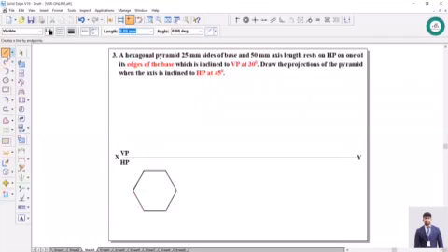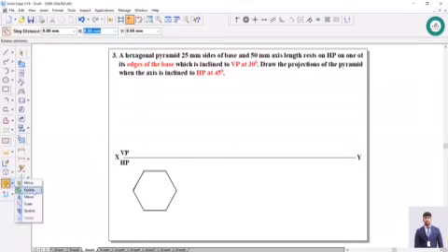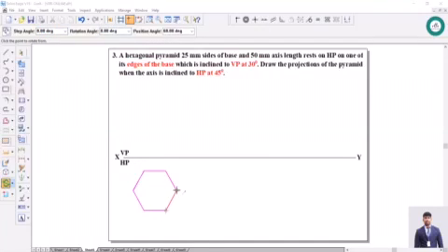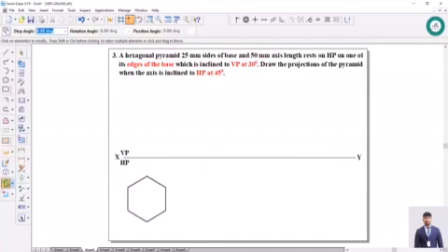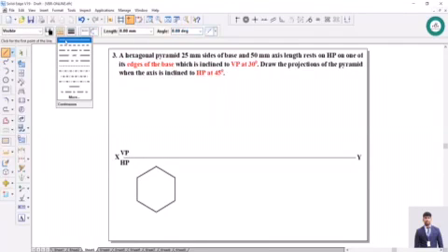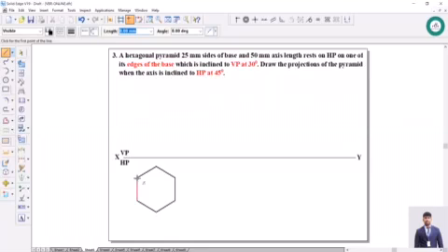Next, since it is an edge condition, go to rotate, select this particular figure, select one edge and make it vertical. So after selecting this, you can move this to a suitable place. Next, identify the center by joining the diagonals.